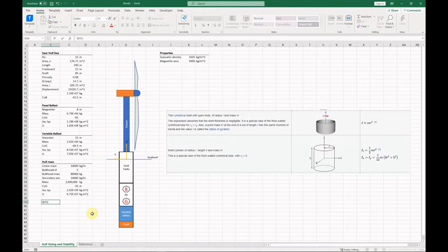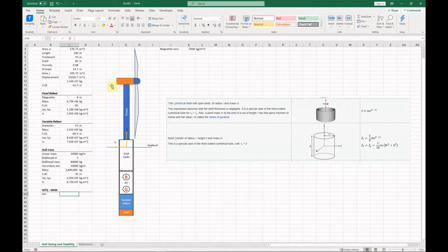Last structure to add is the topside, or, in this case, the wind turbine. A 5 MW nominal power wind turbine is being considered, with a hub height of 100 meters. Let's estimate the mass of the nacelle as 150 tons, and the rotor mass as 80 tons. Total top components mass will be 230 tons. The top component's center of mass will be the same as hub height.